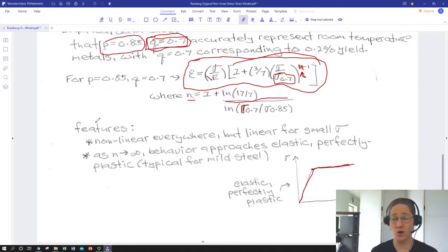Knowing that we've made something from a material that won't work harden means we'll get a lot of strain if we don't keep things in the elastic regime. So that's something important to know about the consequences of maybe not designing properly. But of course, we will be using safety factors and keeping things in the elastic regime to avoid that. So this is mainly a consideration if you ever need to worry about forming materials, so getting the shape you wanted in the first place.